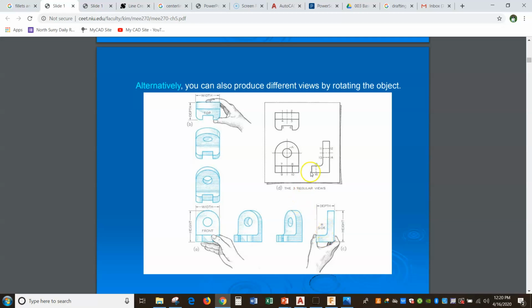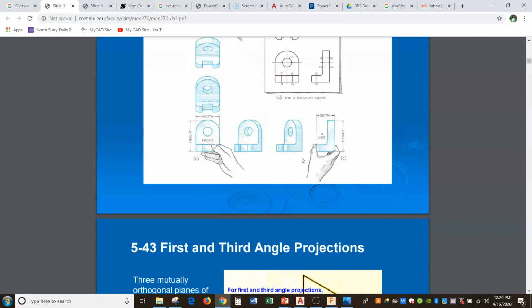We've also got center lines and hidden lines. These are hidden lines. We see them here also, short dashed lines. And then we have center lines. Here's one, and here's 2 crossing. These are used to show circularity or symmetry. The hidden lines are used to show features or edges that we can't see. We'll get into them a little bit later.